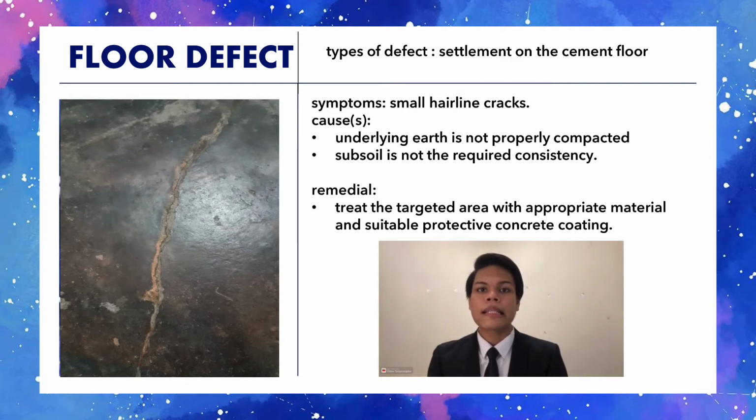So the remedial is that the concrete cracks must be treated by targeted injection of appropriate material and followed by a suitable protective concrete coating, which depends on the depth or width of the cracks.